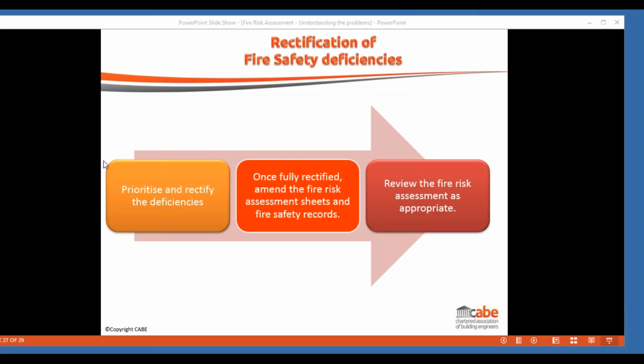And who's required to read or understand the fire risk assessment once it's implemented? Well, ultimately the fire risk assessment is there for the use of the person who is responsible in law for the building. So the person who's managing, the person who's occupying, the owner of the premises. And therefore the terminology needs to be such that the person who is there and running the building and who actually is carrying out the day-to-day activity can understand what's being said.